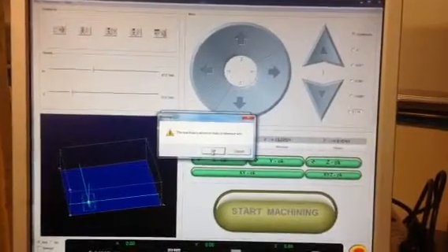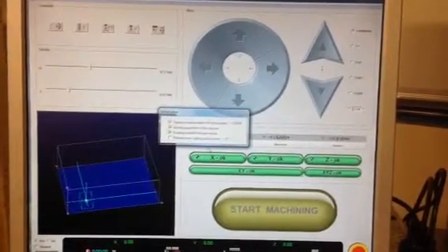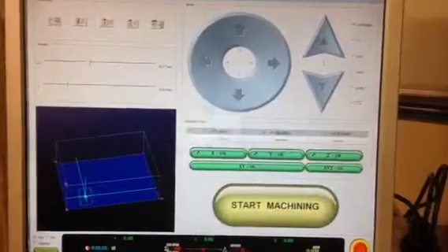And we'll then go through, check communications, and then home the machine. So when we hit OK here, it will send the XYZ to all their home positions. And just say OK, it's working with tool number 1. It's the only tool we specified in this file.